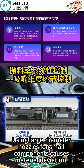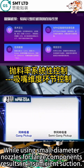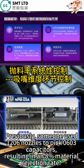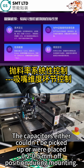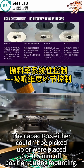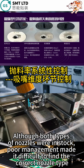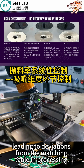Using large diameter nozzles for small components causes material deviation, while using small diameter nozzles for large components results in insufficient suction. Previously, someone used 1206 nozzles to pick 0603 capacitors, resulting in an 8% material rejection rate. The capacitors either couldn't be picked up or were placed 0.2 to 0.5 mm off position during mounting. This was because the program configuration did not follow the nozzle material matching table. Although both types of nozzles were in stock, the stockroom management made it difficult to find the correct nozzle type, leading to deviations from the matching table in processing.